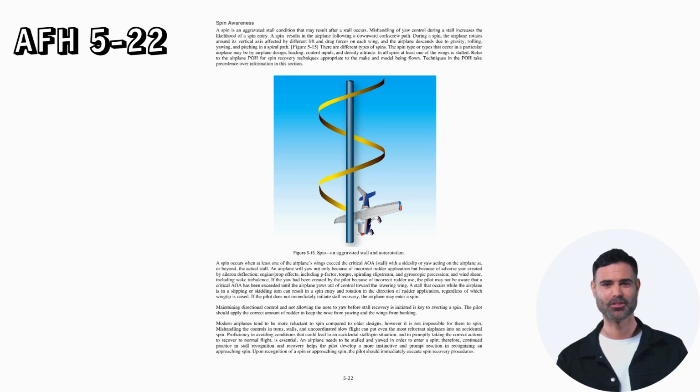An airplane needs to be stalled and yawed in order to enter a spin. Therefore, continued practice in stall recognition and recovery helps the pilot develop a more instinctive and prompt reaction in recognizing an approaching spin. Upon recognition of a spin or approaching spin, the pilot should immediately execute spin recovery procedures.